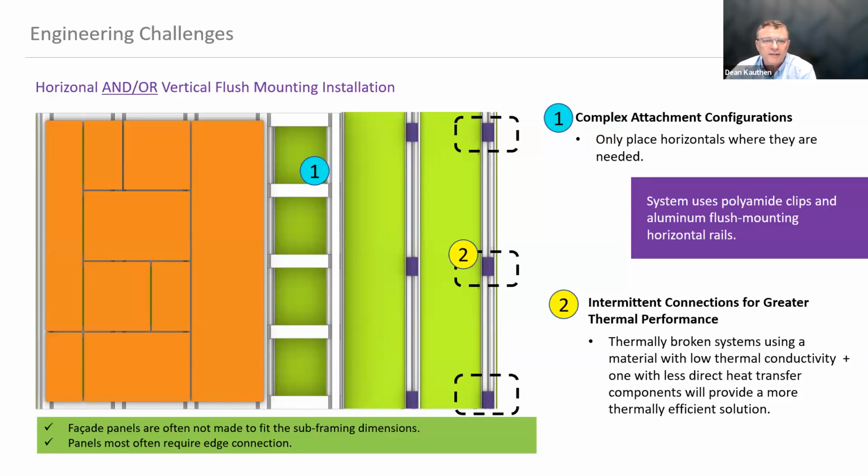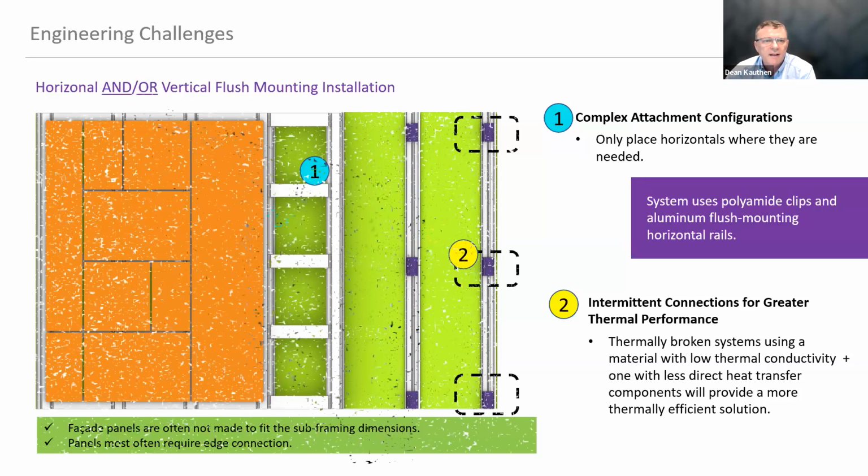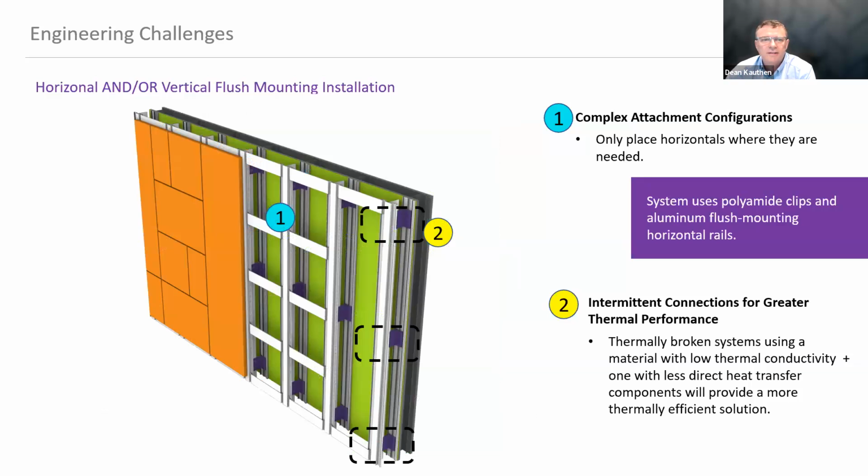They're rather static. They don't have to be changed. They're independent of the cladding attachment on the outside. So what you end up with is a thermally broken system that has ease of installation of insulation and a predictable layout of support for your exterior cladding.